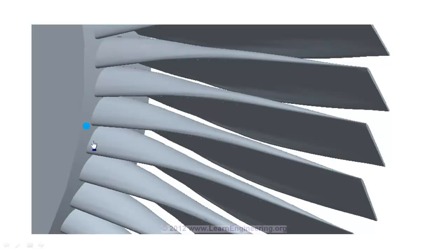When high-energy steam at inlet, the steam with high pressure and temperature, flows over such a blade, it will induce a pressure above and below the blade. And thanks to the special shape of the blade, the pressure above will always be less than the pressure below. So, there will be a resultant net force acting in the upward direction. This force will make the blade rotate, in this manner. As the blade rotates, it obviously absorbs some energy from the fluid, so fluid at exit will have less energy compared to inlet. In the coming session we will see how we can predict the energy transfer in fluid.